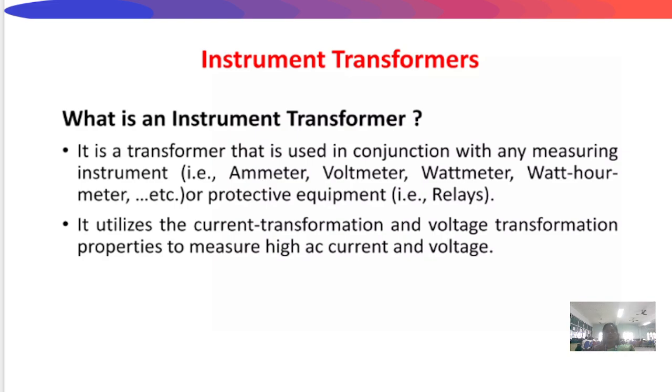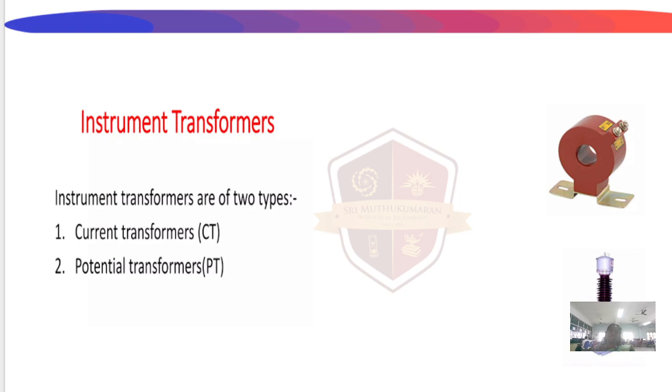But these methods are not suitable for extremely high current and voltages. Why? Because the instruments may get damaged due to excessive current or voltage. So in such cases, we use special devices called instrument transformers.